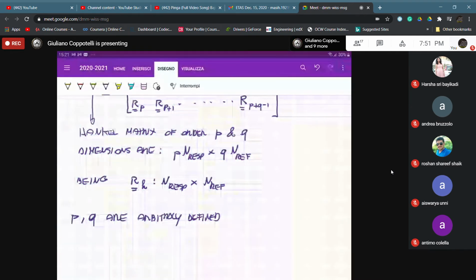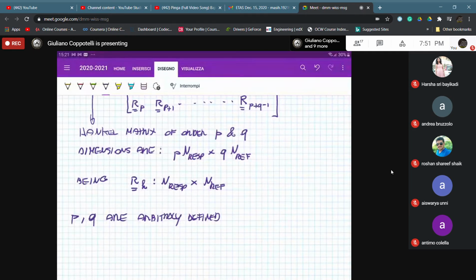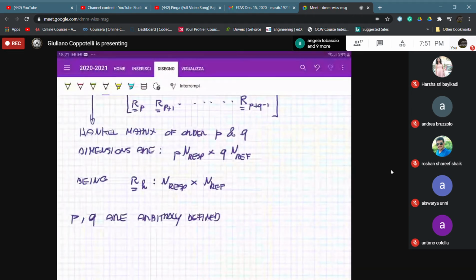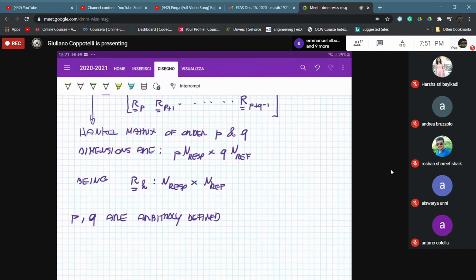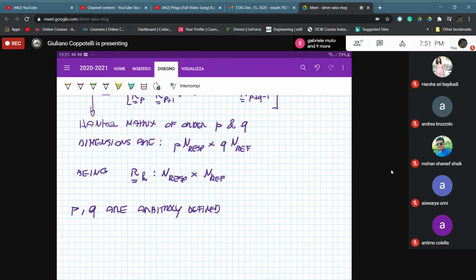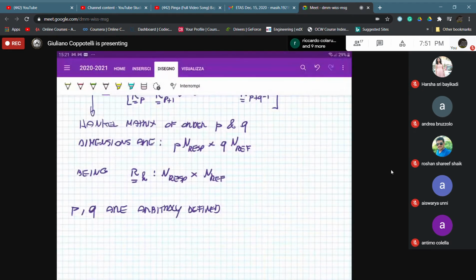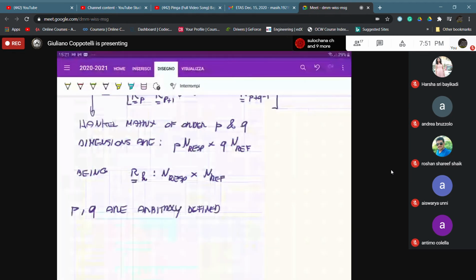If you would like to consider also torsion, maybe you can have two channels at the wing tip, one at the leading edge and the other at the trailing edge. If you would like a more refined analysis, maybe you can introduce additional points, the wing midsection channels. So the number of reference channels increases according to your task and according to your accuracy demand. If you consider, for example, the whole 3D structural dynamic behavior of the wing, then you also have to consider other channels in the X and Y directions, so in the other two directions.